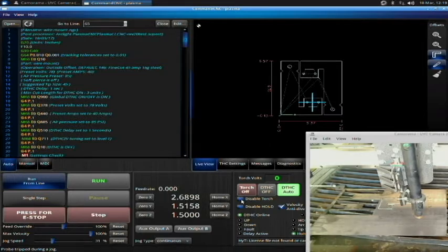Okay, and the same with this retaining cap. This will wear out. It will lose the way it conducts electricity. It insulates from the electricity, and it will lose that ability over time. And so that will wear out, and that will affect your cuts.